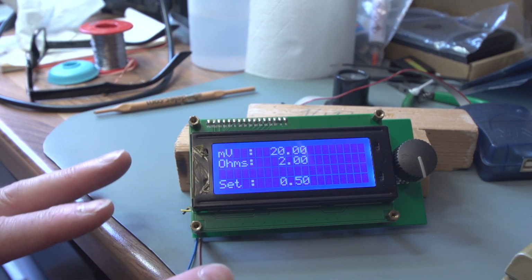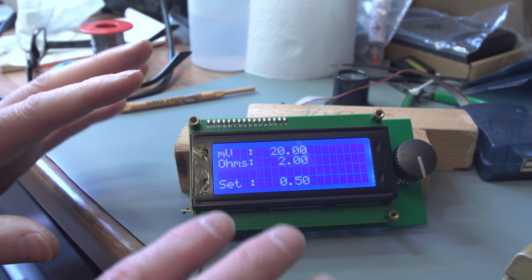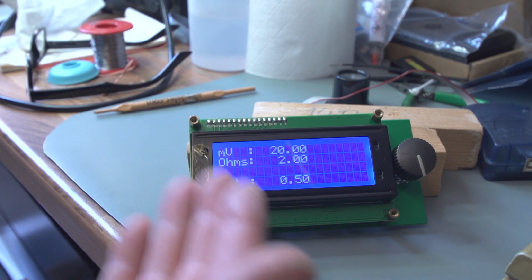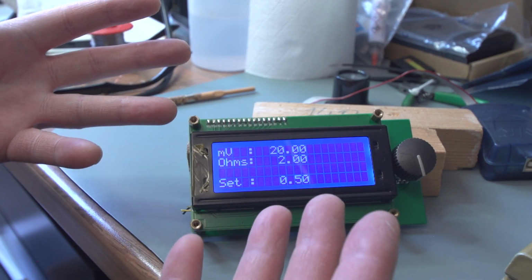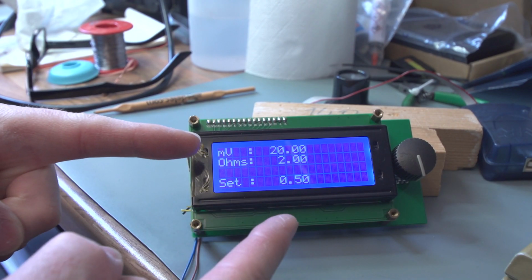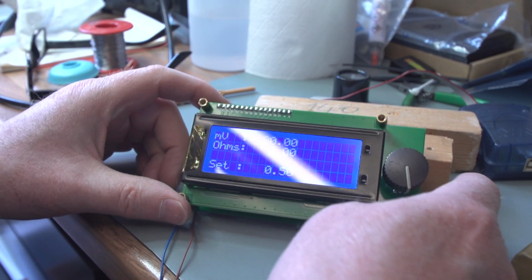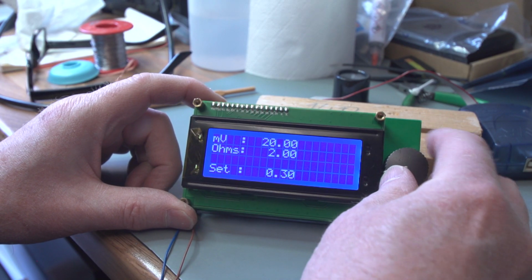So by changing the fuse programming, we've now selected the right clock speed and the right external clock, not the internal slower clock. Now it's running at full speed, 16 megahertz. Well, look, we've got this far. We've got characters on display, and we've got our firmware in. Let's have a bit of a play with the control. What does this do? Aha!